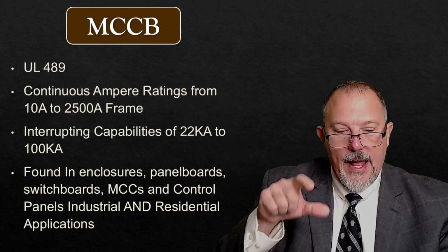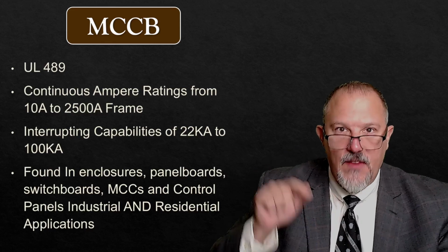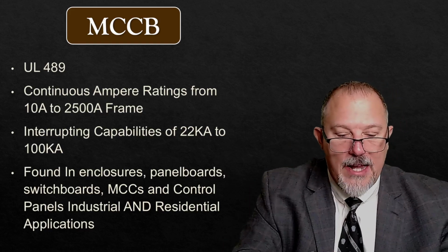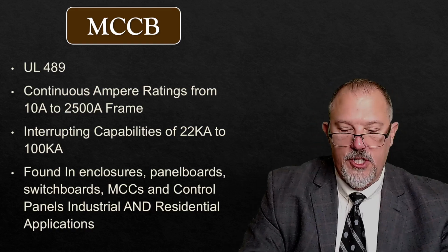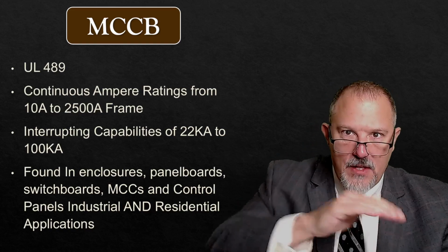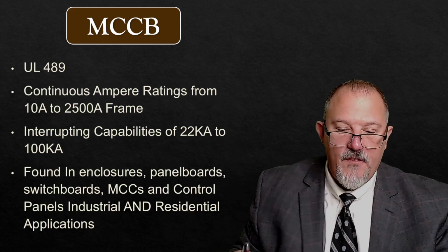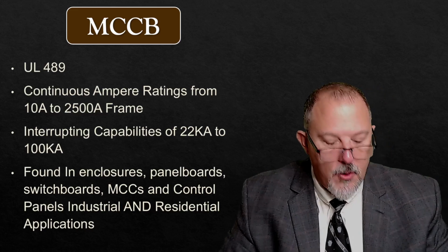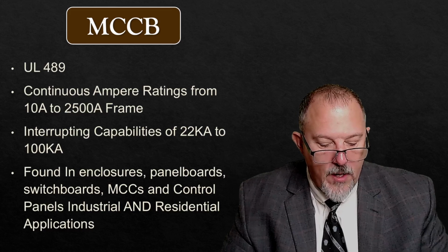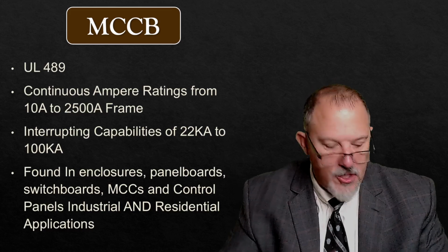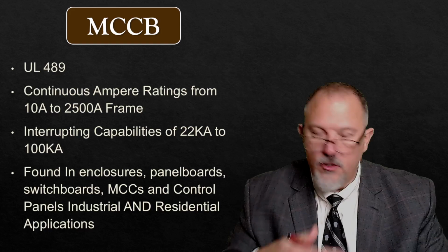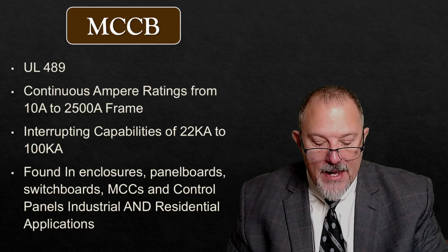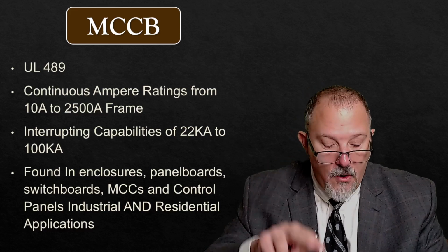Now, if you look at table 130.7(C)(15)(A), it's going to give you different pieces of equipment like panelboards. It's going to give you 600 volt class motor control centers, all this good jazz. But for each of these scenarios in this table, you'll see where it says parameters, maximum of 25,000 amps of available fault current. I'm just reading off of the first row, which is a panelboard, 240 volts and below. Maximum of 25 kA available fault current. Maximum of 2 cycle fault clearing time.